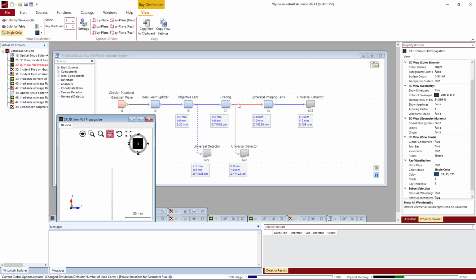And what this red connection here means is that this final lens is going to be positioned in a reflection, so backwards from this element here, using the coordinate system provided by this grating element here. That's what the connections mean. But the engine itself, the non-sequential engine, is going to actually find where the light goes, independent of what we tell it with these connections. The connections are just there for positioning.